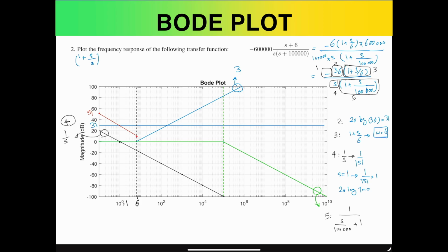Okay. So now that we're done on this, we need to consider what is the change that we just started to see in our diagram. So this minus 20 dB per decade is not changing after this critical point. Similarly, for this pole, we don't have any change. And also this constant number doesn't change at all. However, the only change is only for this 0. This 0 was initially showing a 0 dB.